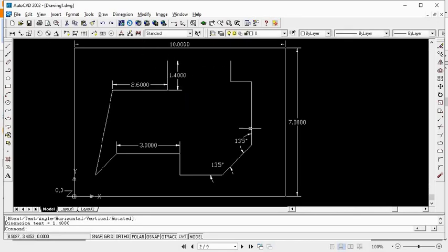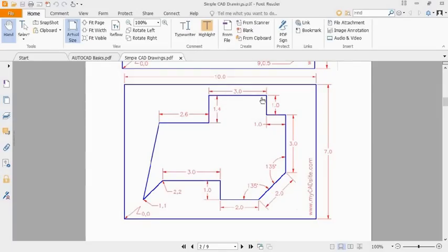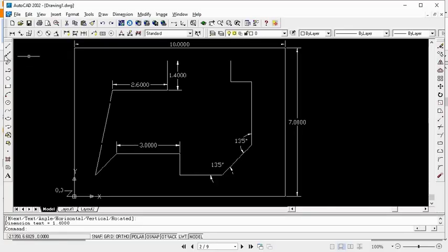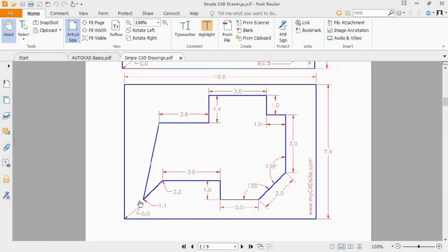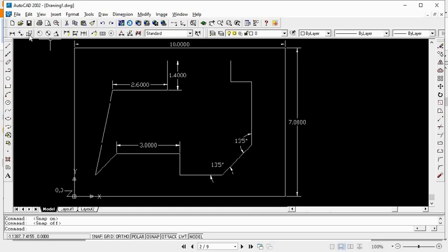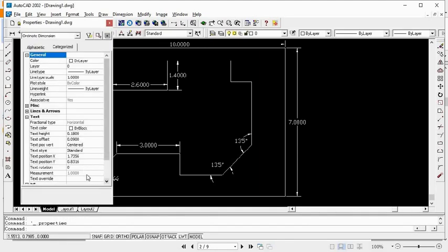So I hope you continue dimensioning to the center of the other points that you have been given, including these coordinates. So take the ordinate dimension, dimension one of the ordinates, and convert it from an ordinate to a coordinate.